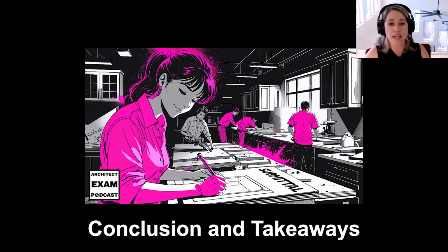Effective submittal management will save you time, it will save you money, and it will also be safer on a project and a job site to have these in place. And if you do nothing else, just really starting with a comprehensive submittal log at the beginning of a project at the kickoff, this will transform your process throughout a project. This will set you up for success. So I highly recommend starting with that submittal log first.